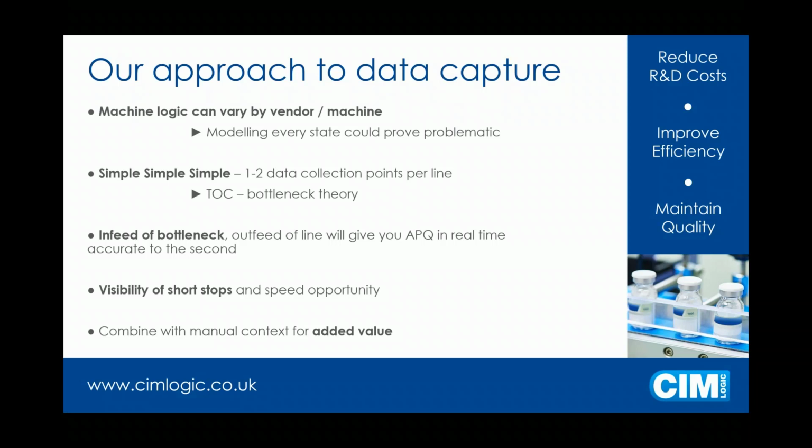But again, particularly in packaging applications, a lot of people tend to find that the Q part of the OEE metric, the quality, is already 98.5, 99%. So for the extra cost that it takes to get that Q metric and get it right, is it worth it? Is it beneficial to us? A lot of people decide not to use it, and they just take the availability and the performance metrics, which you could just do with the one sensor from the in-feed to the bottleneck.